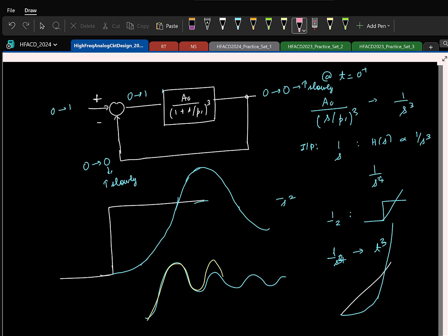If there's more delay, a simple example I give is, let us say it's winter time, you are trying to mix hot water and cold water. You have 2 taps, right? You try to mix hot water first, cold water first, dip your hand in the water and check how the temperature is, and then adjust accordingly. Let us say you're doing it very slow. By the time you sense the temperature, hot water has increased more, so then you will add more cold water. And if the delay is so much, then you might not reach a steady state, right? That's a practical example.